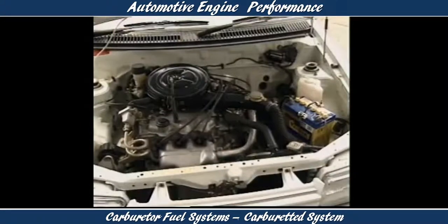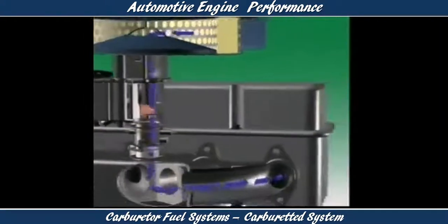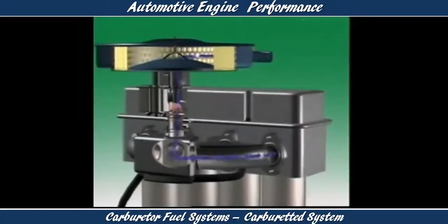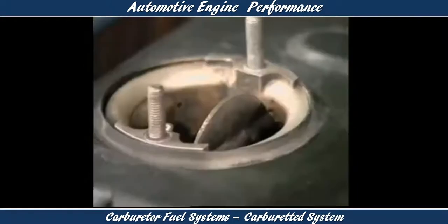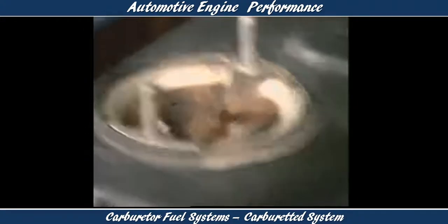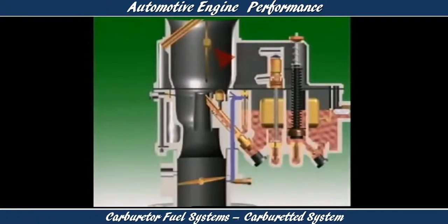When a cold engine is being started, little air flows through the venturi, and there is no heat to assist in vaporizing any fuel that is delivered. This makes the effective mixture of fuel and air too weak to be readily ignited by the spark plug. An excess of fuel must be supplied temporarily to ensure that the proportion of fuel that does vaporize will form an ignitable mixture. A choke valve is fitted to help.